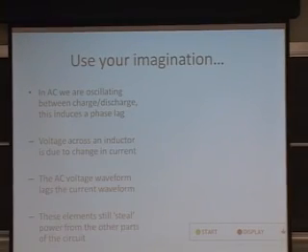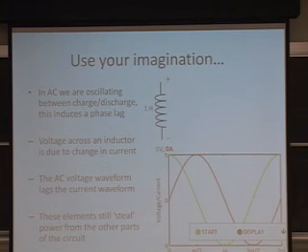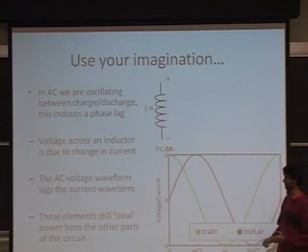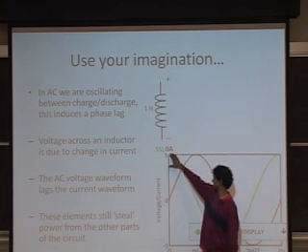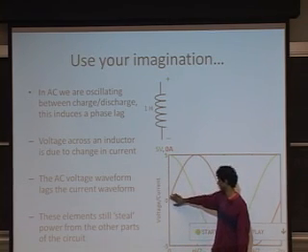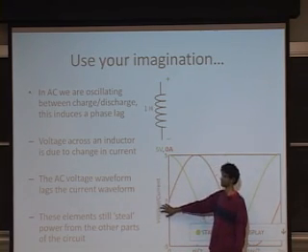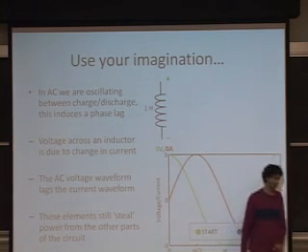So again, for an inductor, we can see the same thing happen. Here the inductor relationship's backwards. The voltage is due to a di dt. So again, if we have max voltage, or if we have zero current, this is the point at which current is changing the most. So the voltage is going to be high.